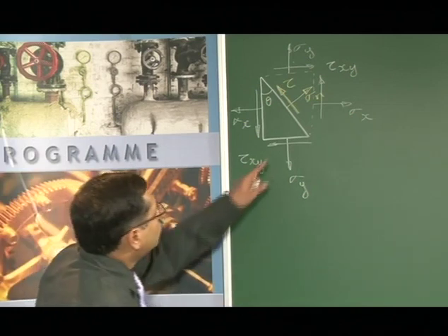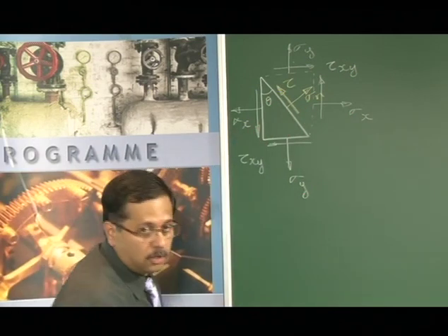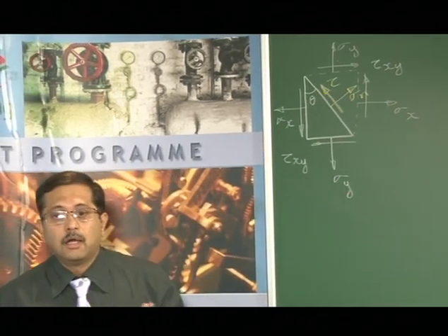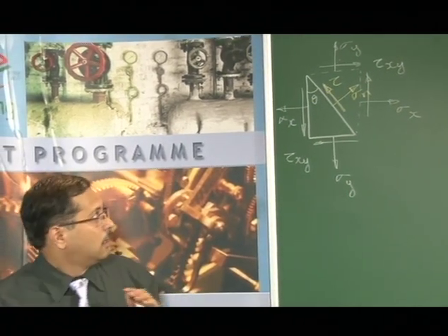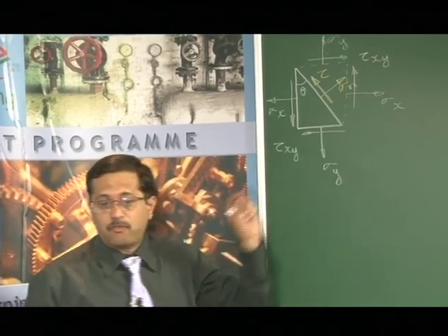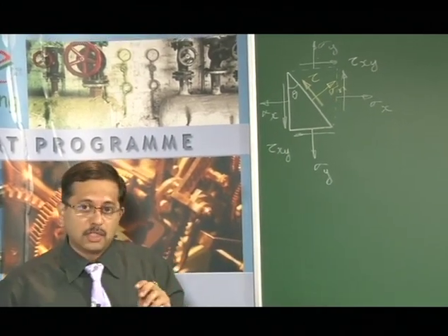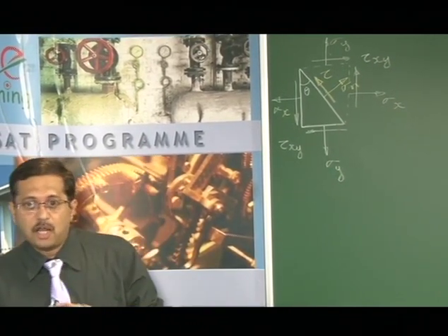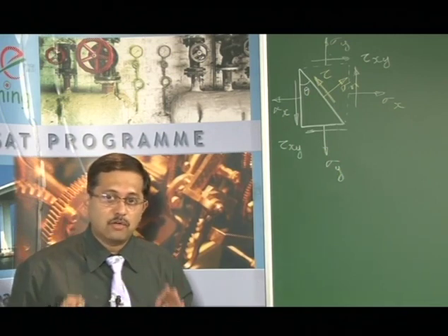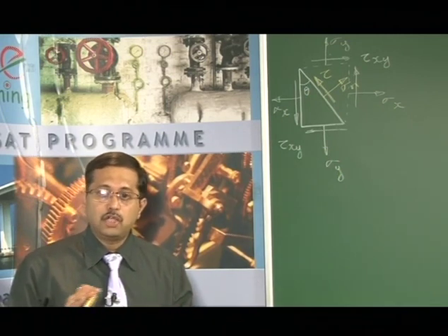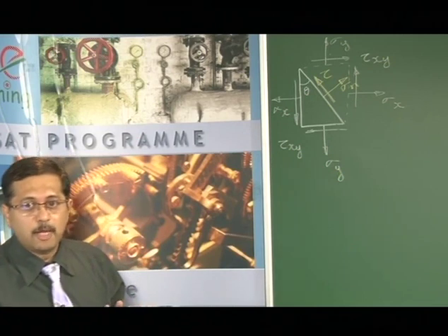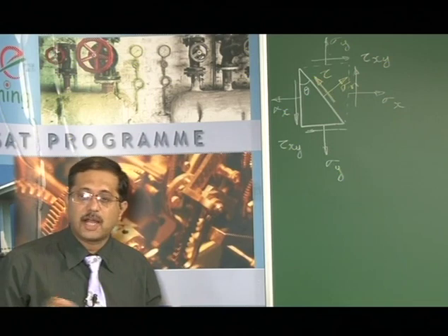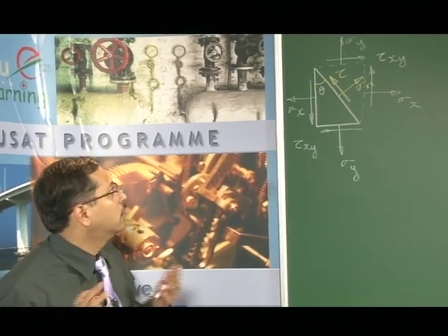Now, how do I get these values? One thing that you should remember when you are looking at stresses and finding out the normal stresses is that the stress whatever is given, first we need to convert it into a force when we are resolving. We cannot directly resolve a given stress along any axis. First we need to convert the given stress into a force, and then only we will be able to find the component along different planes and take the algebraic sum.